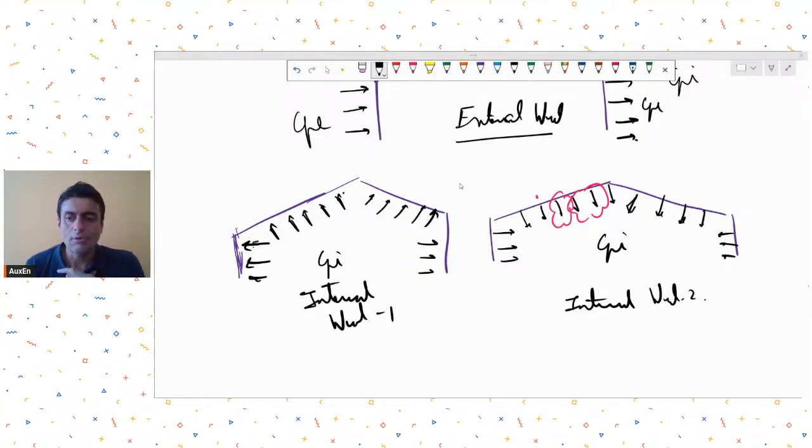So I think what you have seen is this kind of a thing in your STAAD model or ETABS model, that someone in their model must have applied the CPI load case like this, and that's why you got confused, that why these wind loads have been applied in the gravity direction on roof. I hope your doubt is clear. So this is what is happening over there. Is it all right? Okay, so this was his question, Engineer Devlin from Oman.